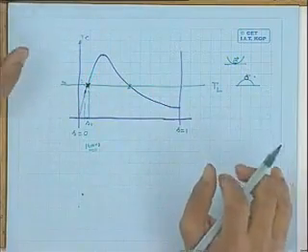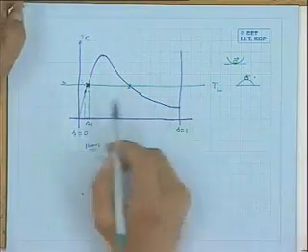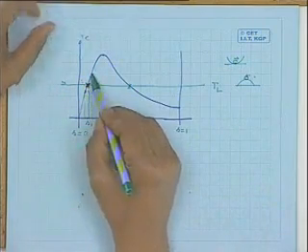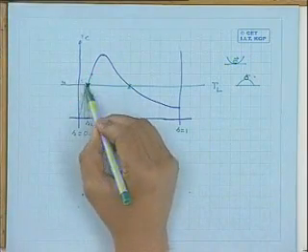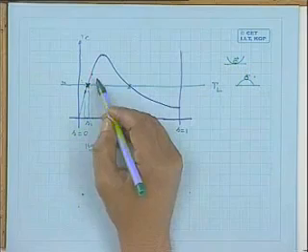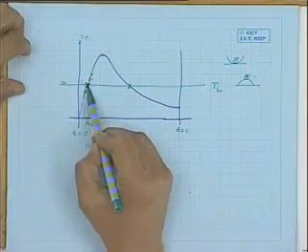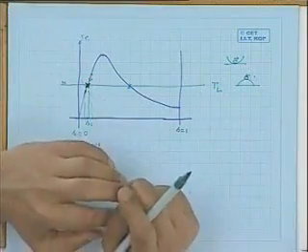Same thing is true if you imagine that the speed is slightly reduced because of some disturbance, the shaft speed slightly reduced by some amount. That is, the operating point slip becomes this one. Immediately you see the electromagnetic torque is greater than the load torque and the machine will accelerate. So on its own, the machine tries to come back to the original operating point, maybe after a few oscillations because of inertia, this way, that way, but it will finally seek this point as its operating point, which is not the case for this operating point, what I am trying to tell.